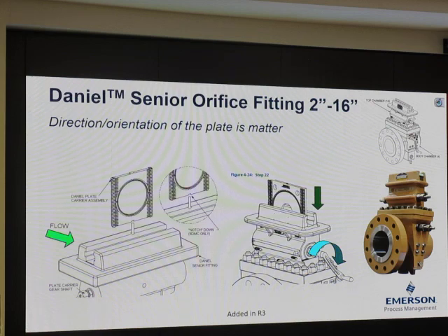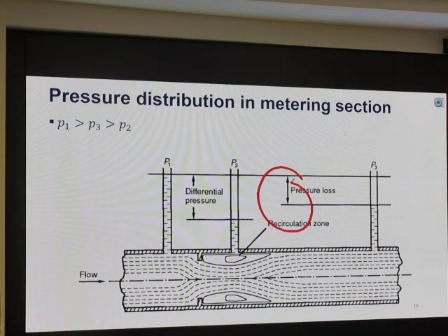Okay. When we take the orifice plate out, what if we flip the side and put it back in? Is that okay? Is that okay, Katie? No. That is going to create a lot of error and no one knows. That is the number one source of uncertainty. They take it out, inspect it, flip it, put it back.